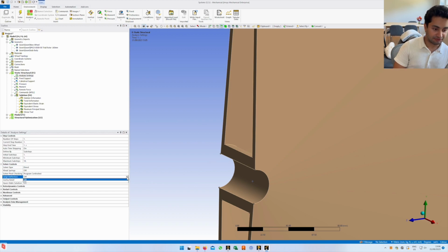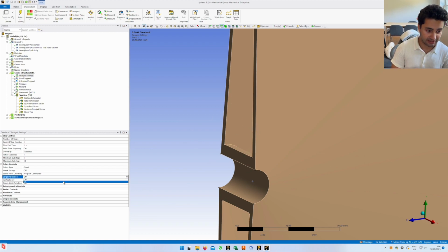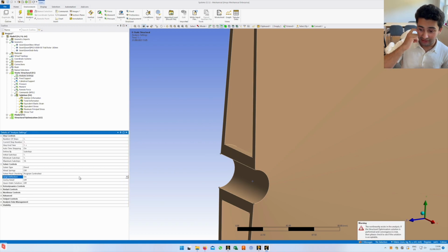Large deflection. Now this is actually how you enable a nonlinear analysis. Nonlinear analyses pretty much at least double or sometimes triple the amount of time your simulation will take. Ansys is quite explicit in the documentation, it urges you to really enable nonlinear analysis if you've got thin walls like this. It was taking sometimes several days for these nonlinear analyses to solve for my model.